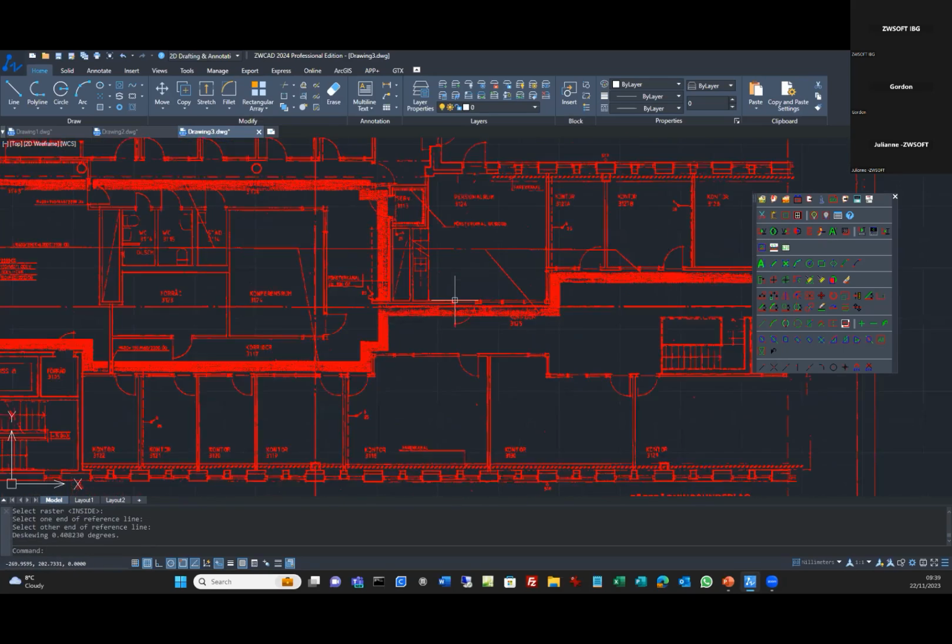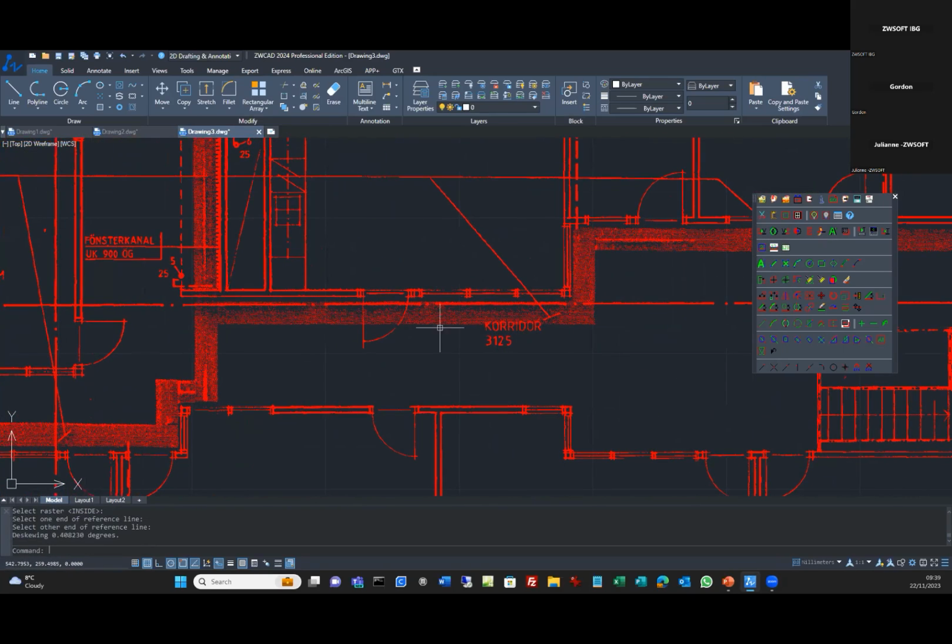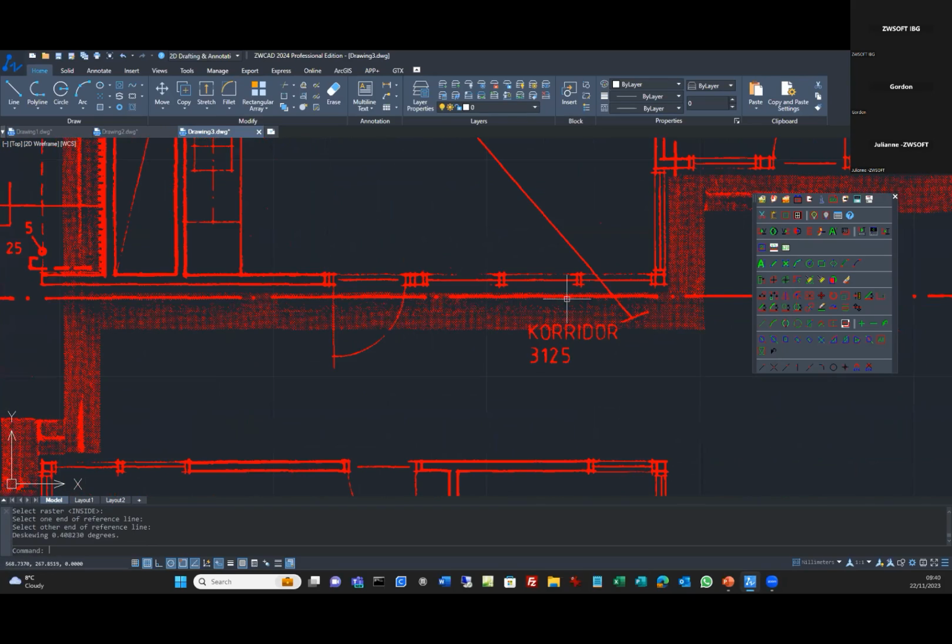We have some ducting along here, which looks like it's all stippled. It could have been some sort of tape or something on the original. So what I want to do is get rid of this ducting because I want to change or repair some of the data within the drawing. So if I say erase, use the inside command again, just draw a box around this data. Everything that's on its own will be highlighted and I can get rid of it.